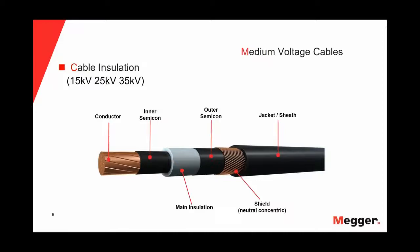We are seeing in the slide the classic single phase cable in which we have a center conductor that could be of copper or aluminum material. Then we have this inner semicon layer. Next, we have the main insulation of the cable. We will continue with the outer semicon layer. Then next we will have the neutral concentric shield of the cable, and finally we will have the jacket or sheath of the cable.